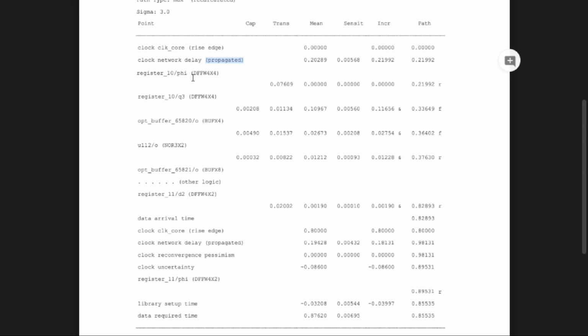All right. So other things is like you have the cell names present. This is actually the library name of the cell. It can be different with respect to different libraries. You will need to get that information from your vendors or the foundry, what is the meaning of these cells. All right, cell names. One common thing is usually the X thing, X4 which is mentioned here, or an X8 mentioned here. Basically that's the drive strength of the cell. So that is one common thing. And here you can see that this is a buffer, this is a buffer, and it's saying D flip-flop, and many others.